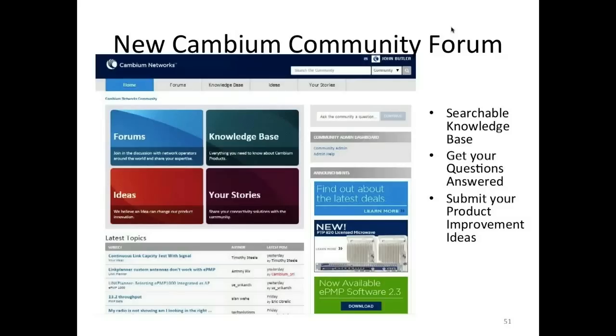And what ePMP does is it has a very, very fine-tuned adaptive modulation that can change gears very quickly, very frequently, while keeping that throughput high. We obviously have an ARQ, an automatic repeat request mechanism that runs underneath. So if there is interference-caused packet loss, we are recovering, retransmitting. And we're doing all of this underneath the layer to present you a system that will perform better in the presence of outside interference. Okay, great.